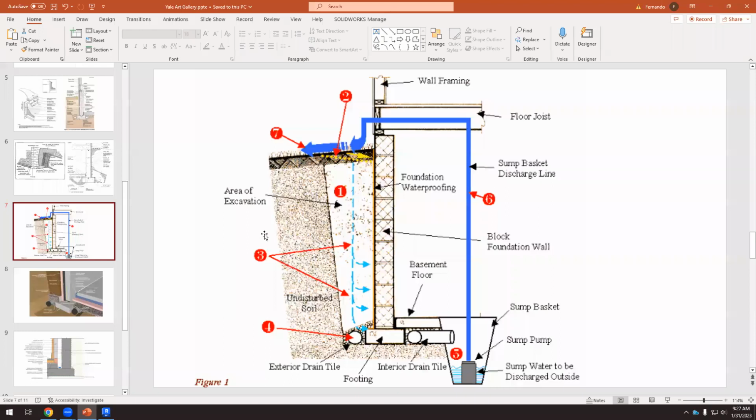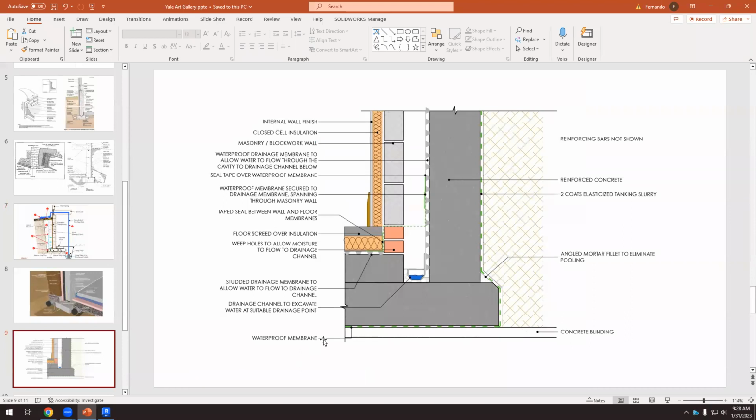Drainage. Again, you can dig this and then put the drainage at the bottom of that and cover, but I think it's better if we create like a base to rest the drainage pipe. So you see that here we have this drainage, but we have created it like this so that the V shape can be adapted to this. So it's not just throwing the drainage pipe. We have created a support and that protects this drainage pipe.